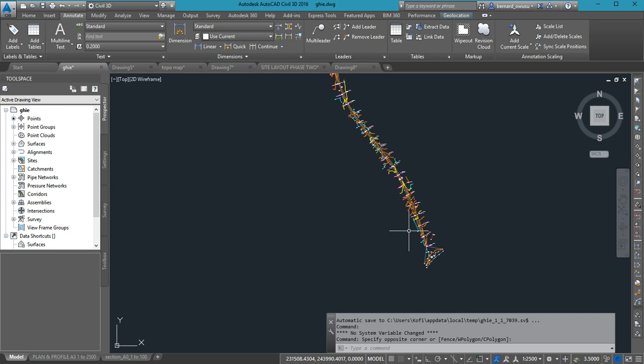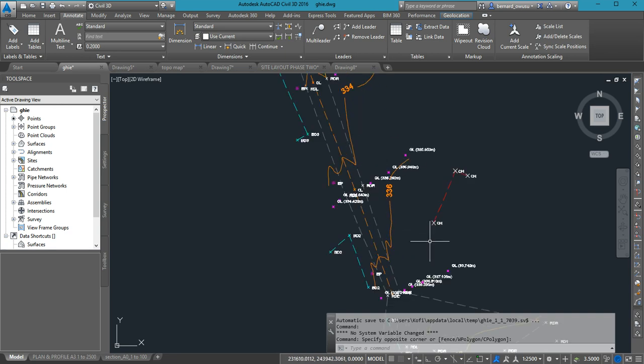As I said, before you do your horizontal alignment design, we are doing a simple single carriageway, and we are saying that the width of the carriageway is 7.3. We have shoulder 2.5, drain 1 meter, and that is it. So at worst, the minimum total width that we should have should be about 14.3. Good. Please take note of that. But that is one option. You can decide to use a different width, 3.5, whatever you want to. But we are going to define a center line.